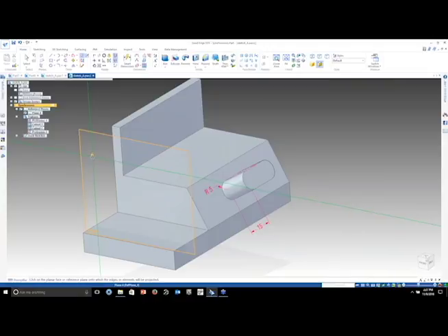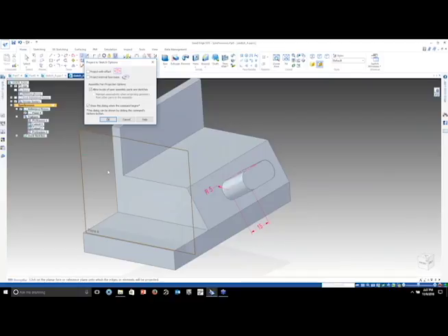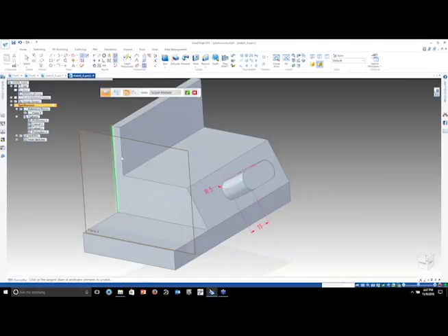But instead of actually drawing the sketch this time, we are going to use what they call project to sketch. All right, so this is going to actually take the face of a geometry, whether it's parts from an assembly or parts from the part file. So once again, you notice again F3. All right, so I'm going to lock to that.